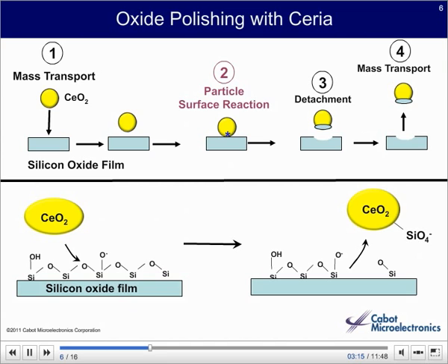This is an example of how ceria, cerium oxide, behaves with a special chemical affinity for polishing silica. Some researchers call ceria polishing the chemical tooth because they believe it takes a bite out of the silica surface. But mostly particles are believed to be mechanical, rolling and sliding on the surface like sanding wood.